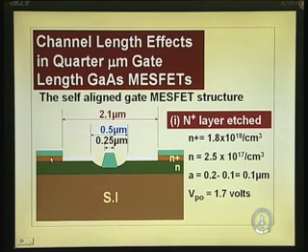You do not want velocity saturation, you want Ohm's law to hold good. So, a small current will flow. Measure the voltage drop between the source and the gate. The whole thing is the IR drop due to the current flowing. So, you measure the voltage drop and the total drain current, and the total voltage drop between these two divided by the current gives you the resistance between these two.